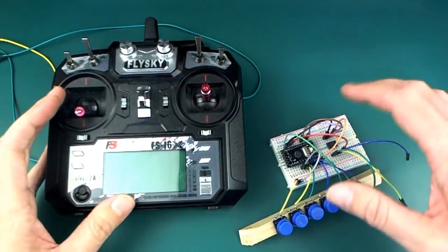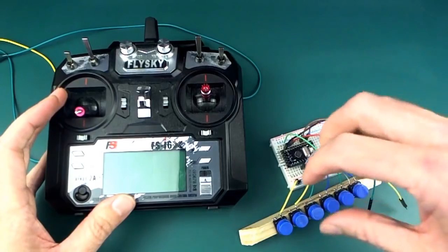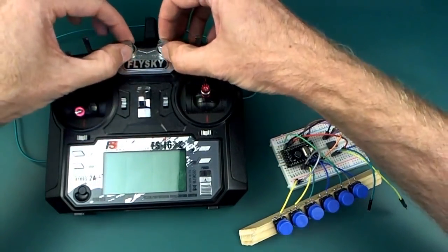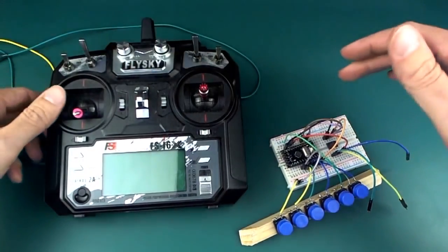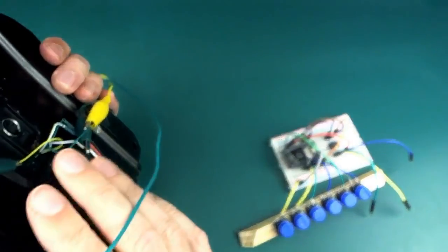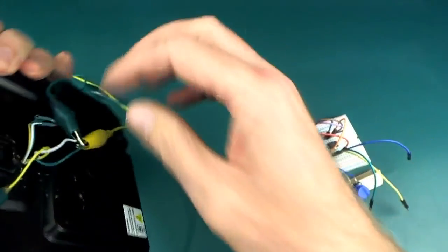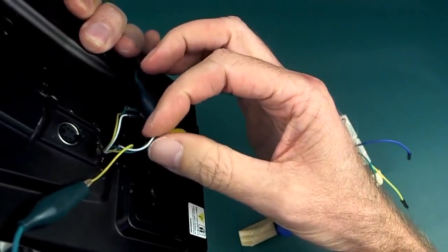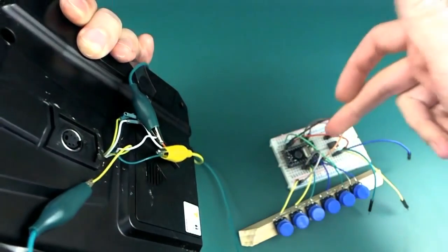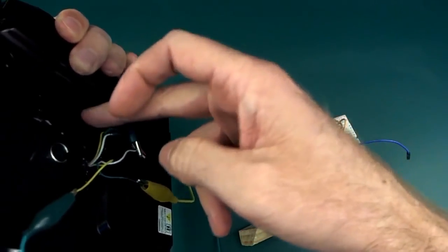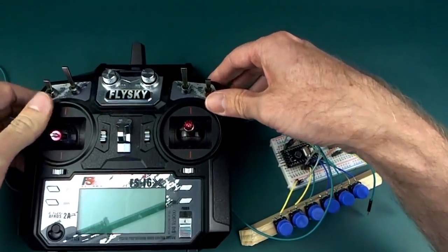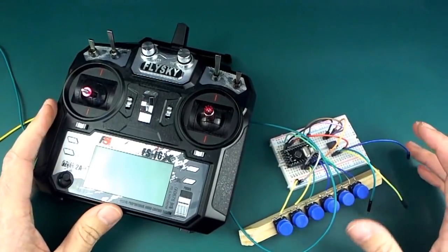All that remains is to tidy this up, maybe put it on a proto board or something and mount it up here, and probably just take these pots right out so that this is a little bit flatter and sort of put it on there somehow. And I'll also have to figure out somewhere inside here to get that 3.3 volt power from, because you cannot use these same wires for power, because what you're going to be doing is putting a resistor between them with your digital potentiometer. So you're going to need other wires or another location on the PCB in here to get your 3.3 volts from. That shouldn't be too hard, and I don't think there's anything to be gained from anybody watching me fumble my way through that.